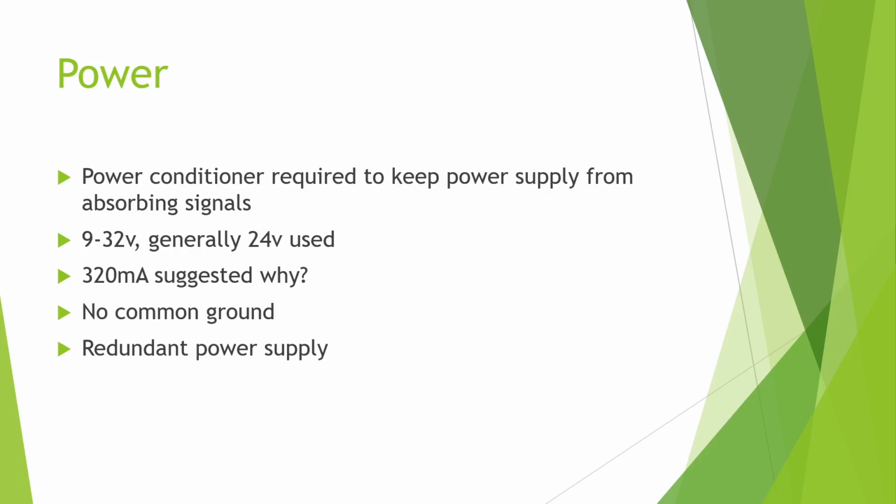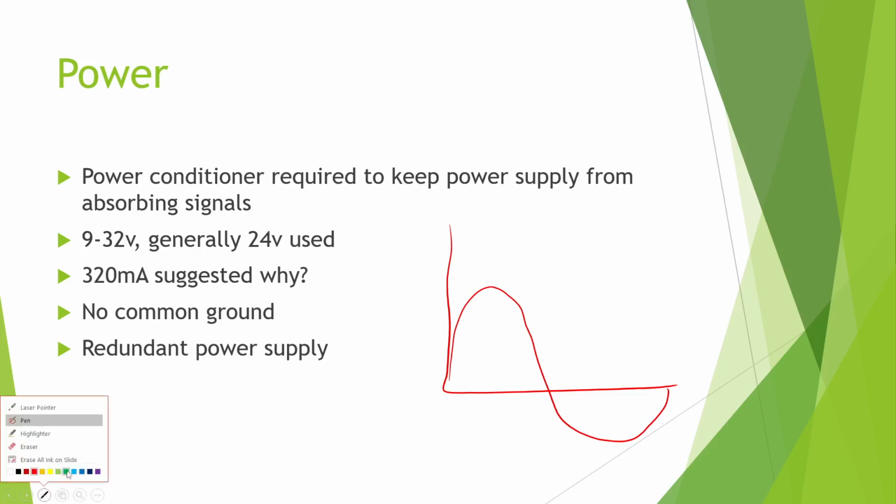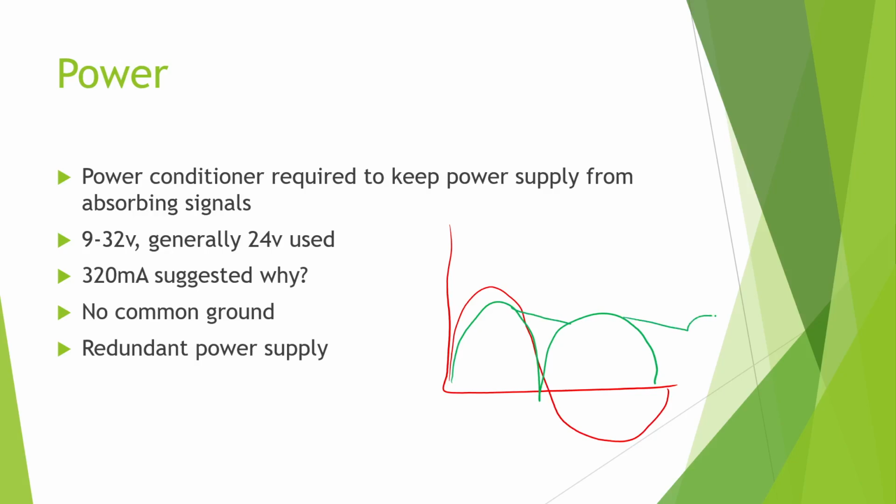All right. Fun little side note here for those who don't know how power supplies work. You take your AC in, and then we rectify it. All right. And by rectifying it, we take our AC and it looks like that, and it now becomes pulsating DC. So it's now doing this. All right. So it's all on one side. Then you throw a capacitor on that, and it does this. All right. So we never make it back down to 0 because we charge that capacitor up to full, and then as the AC that's bouncing goes down to 0, that capacitor is draining, and then that AC comes back up, fills the capacitor back up, and does it again.